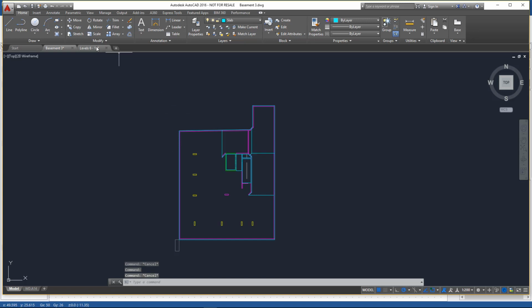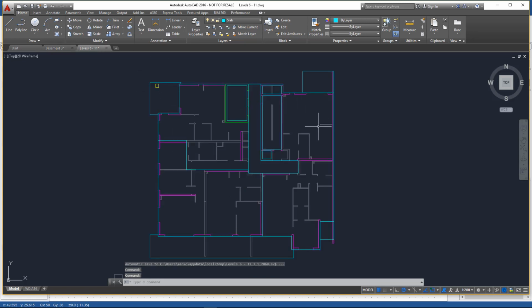Now let's go to one of the typical upper floors and see what we've done here. So the column, there's just one of them, again drawn into its own layer, single closed form polyline. We have the wall panels drawn as single closed form polylines wrapping around each individual panel. The shear core itself, a single closed form polyline. And basically areas that will have different loading are defined.